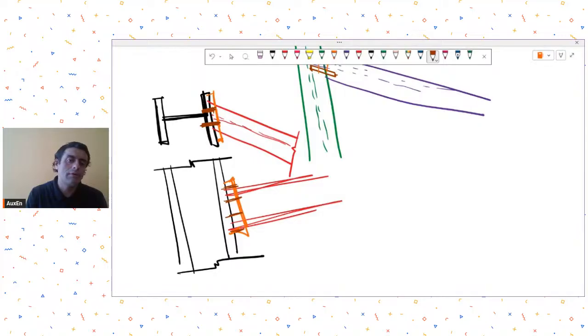Its alignment should be carefully observed. For that you will have to check your actual assembly configuration, and then you provide stiffeners or whatever. So this is how a moment connection can be created for beams which are not meeting perpendicularly, inclined to the column. And for beam to beam, as I just told you, you may use the cut or bent cleat, or you may use the fin plate connection.